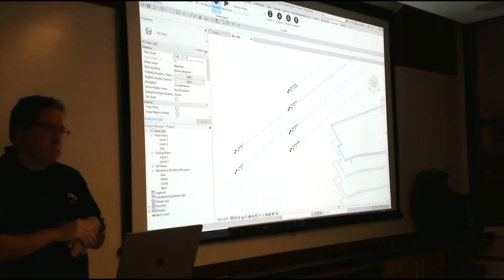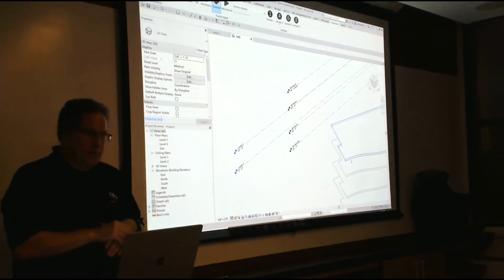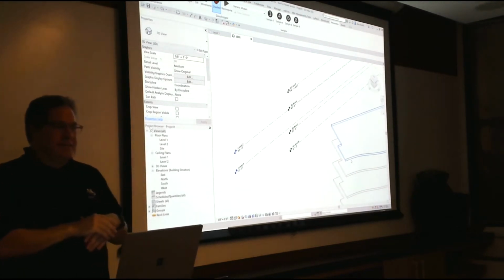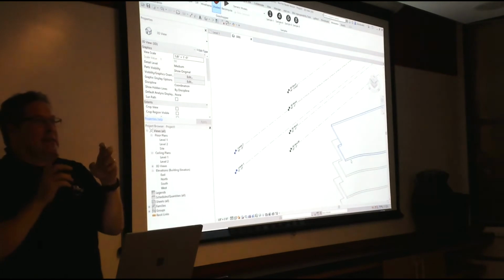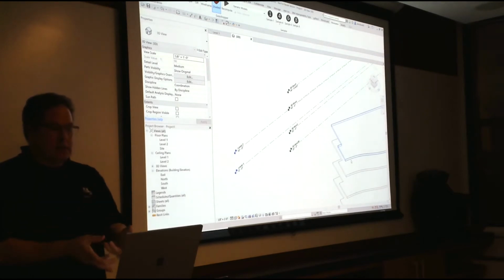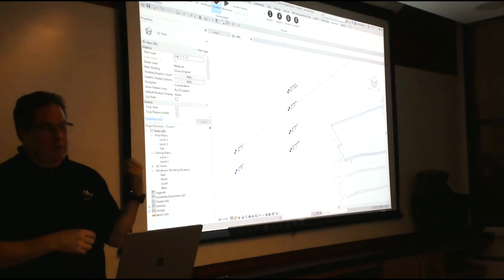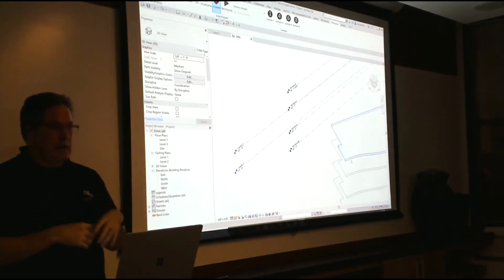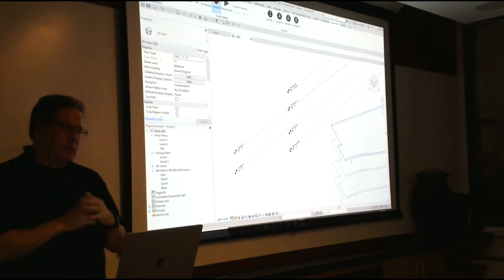Have you seen people run form finding and Kangaroo stuff? Yep. Yeah. Now I would highly recommend maybe not baking a Revit object at every step, right? Yes. But you're going to see here that Grasshopper previews in Revit just as fast as Grasshopper previews in Rhino. So yes, you can do that and then bake it into Revit when you're ready.